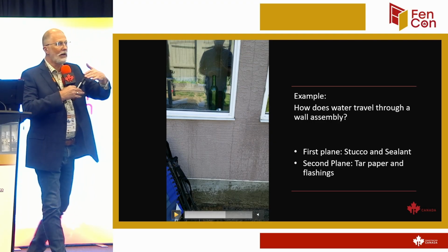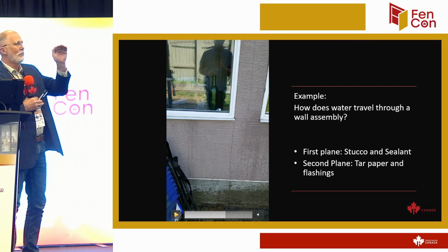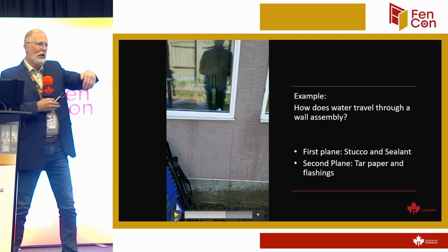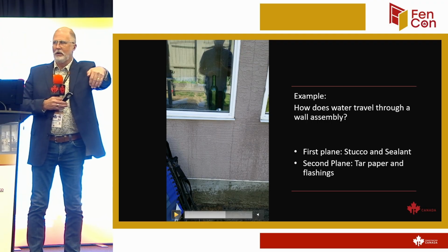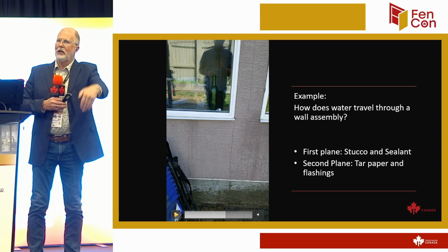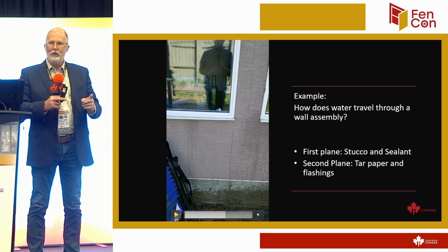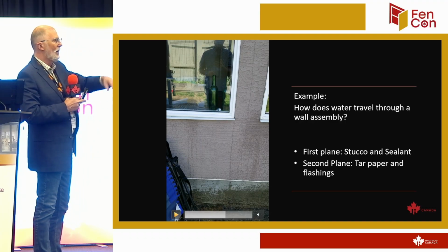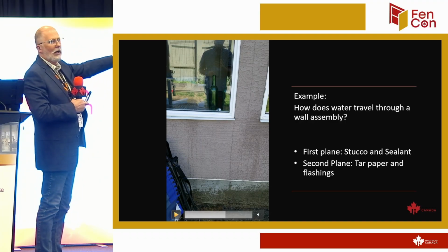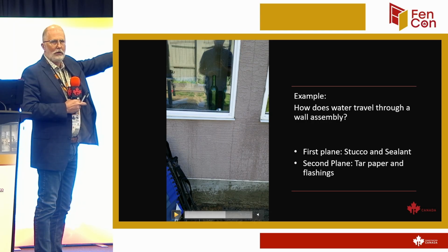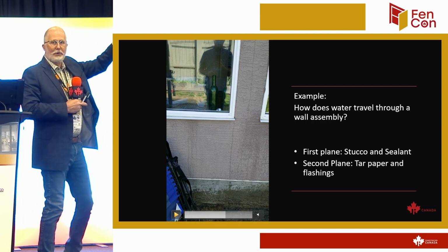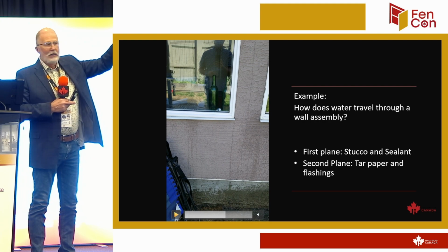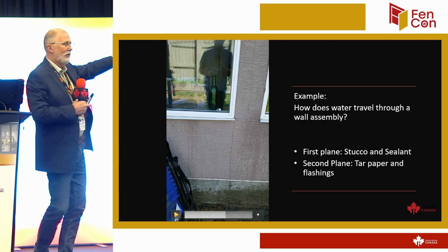So it builds up enough of a hydraulic head, it lifts the water up and over that joint, and now it's on the inside. And now it hits the floor joist, and now it's on the inside of the sheathing, and now it's running down the inside of the sheathing, hits the window inside, because they've sealed the window on 4 sides. Now on the inside, it hits the sill pan, and now it's draining out the way it's supposed to. So even though maybe 3 times a year this building will have water getting where it shouldn't, it's not going to suffer catastrophic failure in the long run.